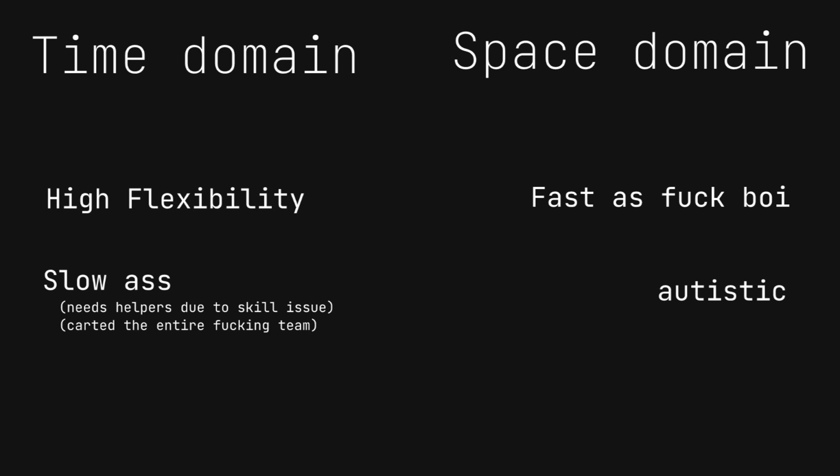If we're doing some specific work, a lot of times, the FPGA is a good candidate. But if you need to do a bunch of different things, each one only once, well, you're going to be spending a lot of time waiting for the FPGA to reprogram itself. In short, processors are great when what you need to do is completely random, and FPGAs are good when what you do has a lot of structure and repetition.